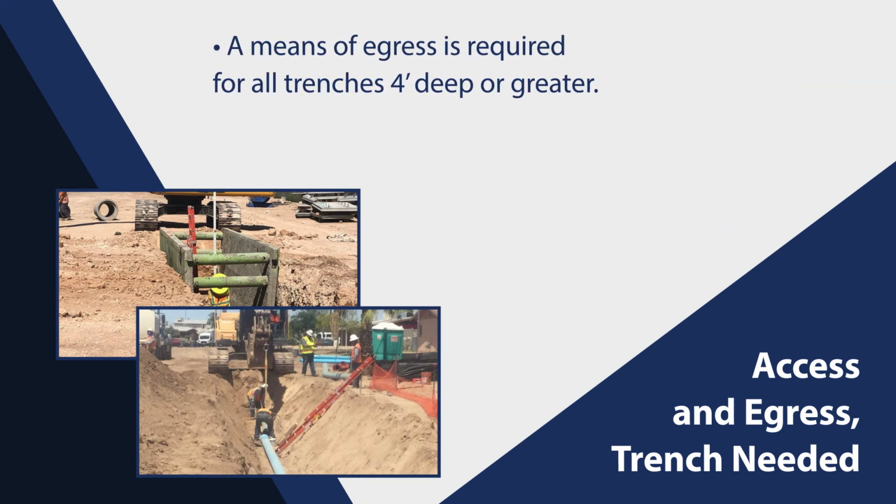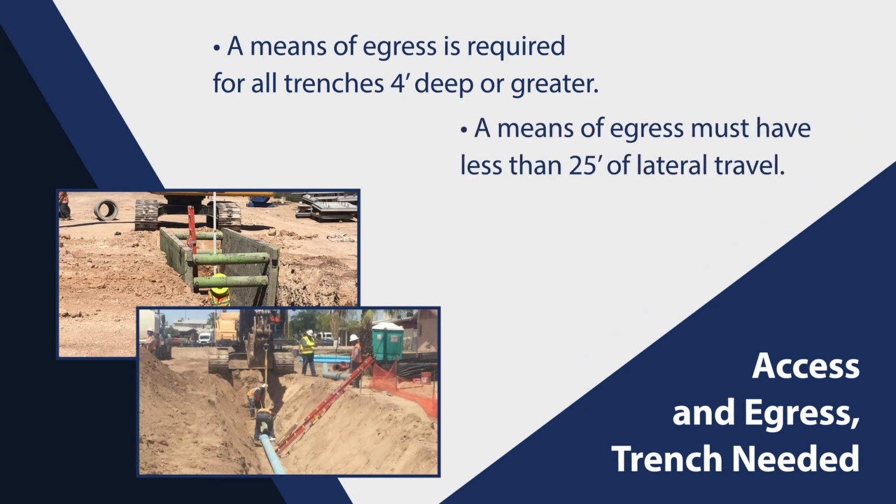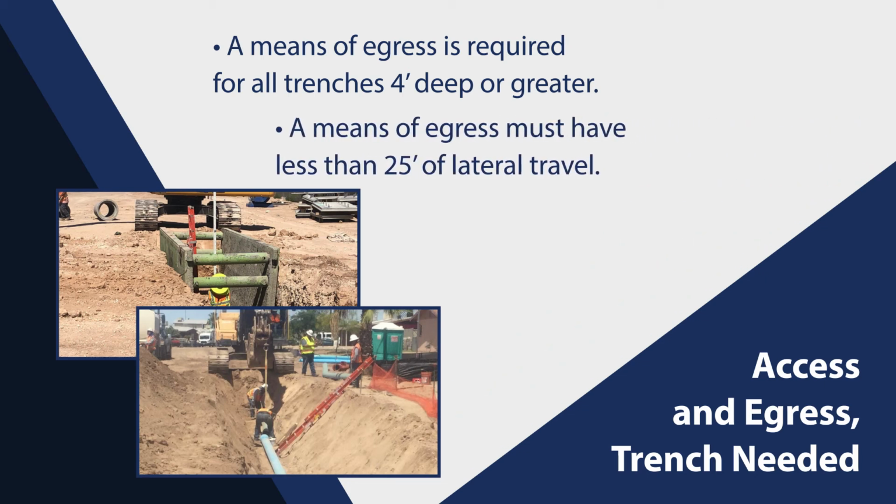You must provide a means of egress for all trenches that are 4 feet or more in depth. A means of egress must also be provided with no more than 25 feet of lateral travel for employees. In these cases, ladders are the most common method of providing a safe means of egress.